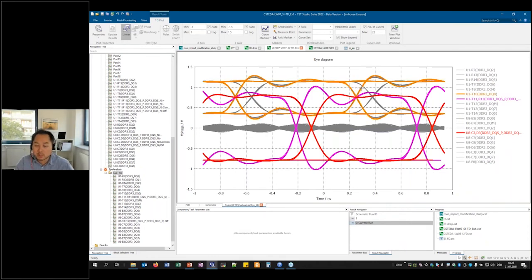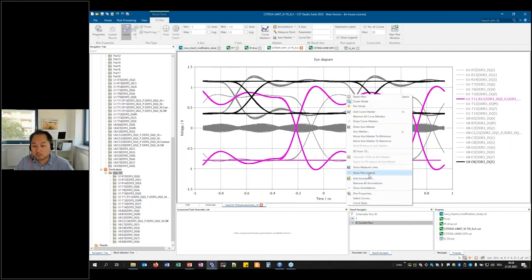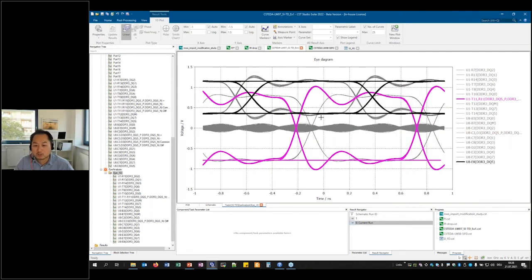You can also study the position of, for example, the crossing point between this signal and this signal, and then you can directly place the measure line. You can measure directly the distance. So this will be the delay. I just have a slight delay here. So this is typically the SITD simulation results that you are observing.